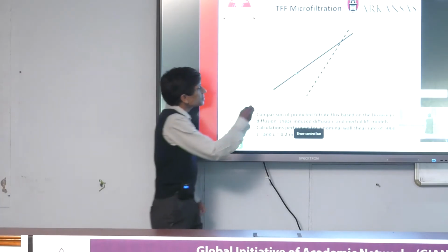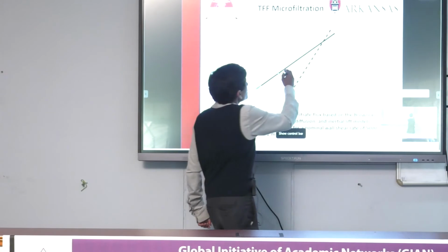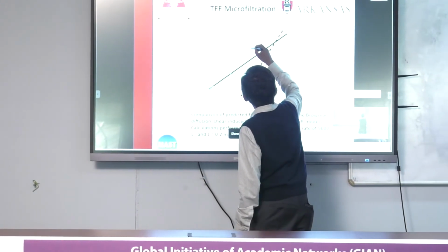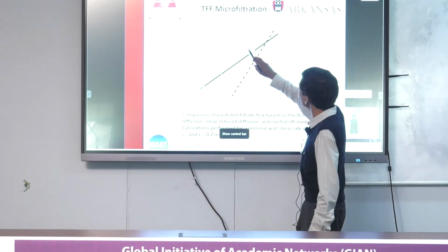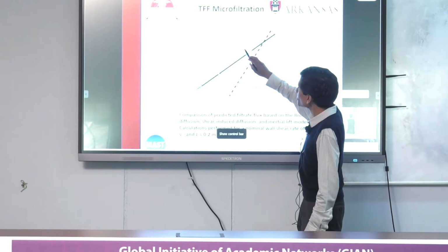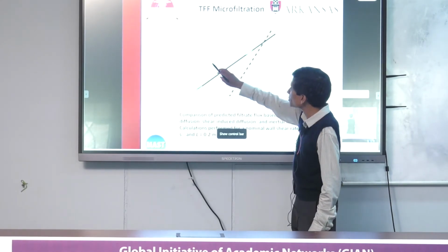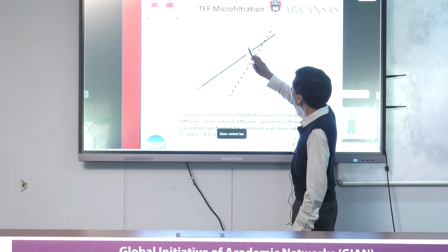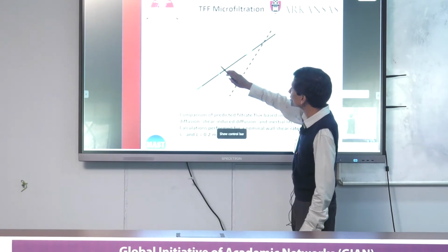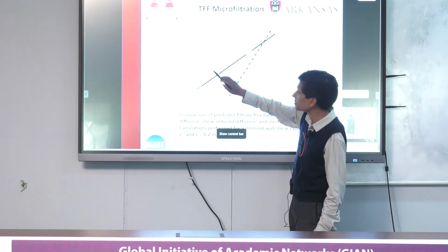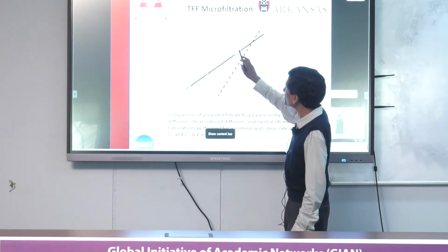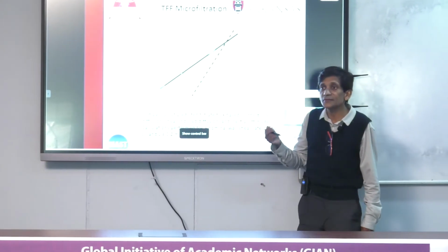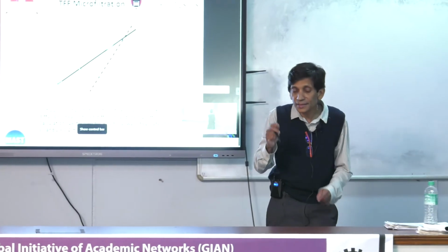If you look at this one, this is going to be shear-induced diffusion. You can see here that it goes linearly with wall shear rate. This one goes with wall shear rate to the 1/3 power. It increases with particle radius. This is decreasing with increasing particle radius. And both of them depend on the length to the inverse 1/3 power. So here's another interesting point there.